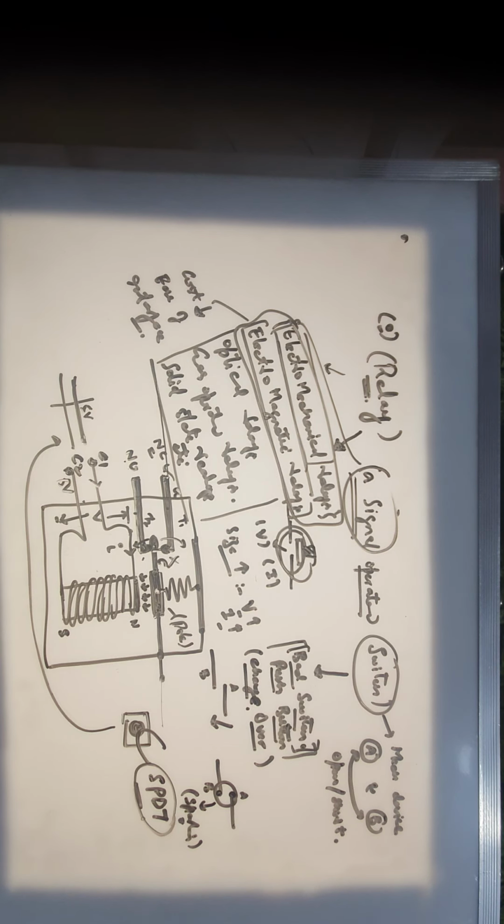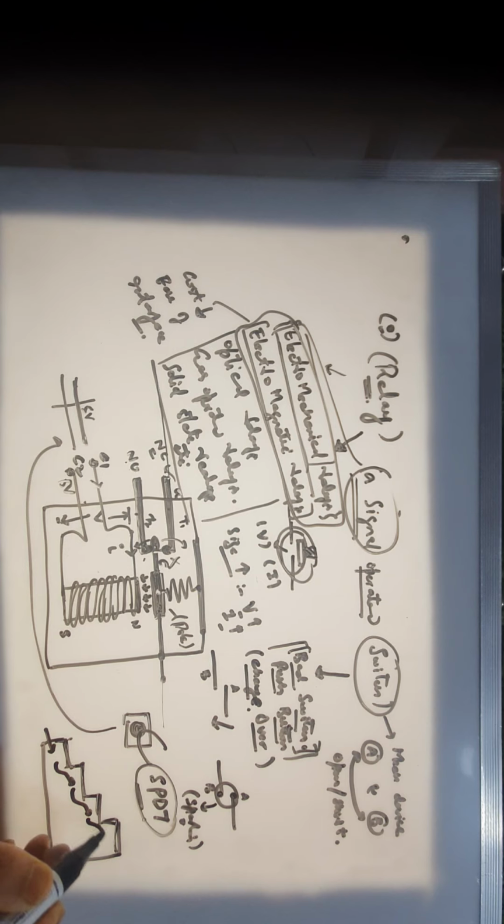And this single pole dual throw relay will act as an electrical actuation system that will actuate a bigger thing. And you will see in future that the bigger thing at this point of time, that means the linear actuator, will be a small thing for some other big thing like your hydraulic or pneumatic actuators, which will then be actuated by it. So it is a ladder mechanism. If we have to control some very big thing, you do it in a staggered manner. You first use a small driver to drive this, it then drives this, it then drives the big thing.